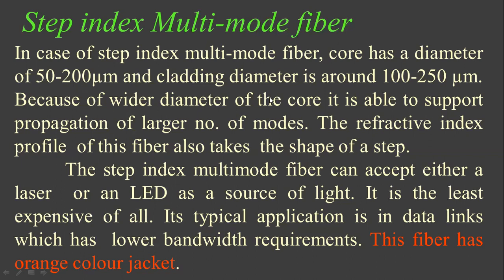Because of the wider diameter of the core, it is able to support propagation of a large number of modes. The refractive index profile of this fiber also takes the shape of a step, and hence this is called a step index multimode fiber.